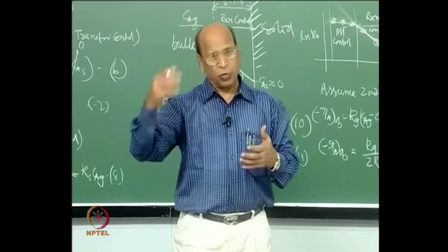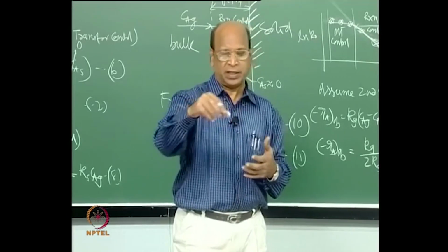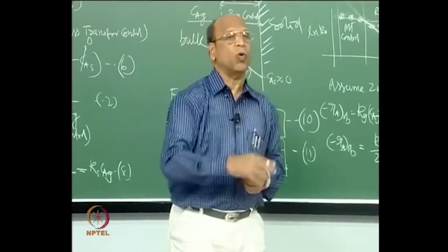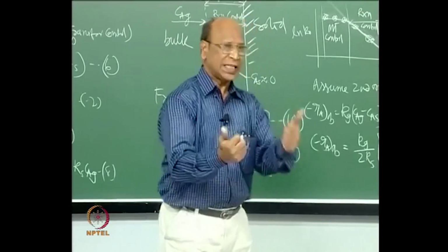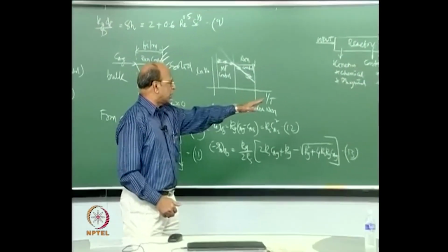If I have a liquid phase reaction where the residence time is still very small, that means the reaction time is very small, and I can still go for plug flow. That is again another thumb rule we use. We have plug flow and mixed flow.